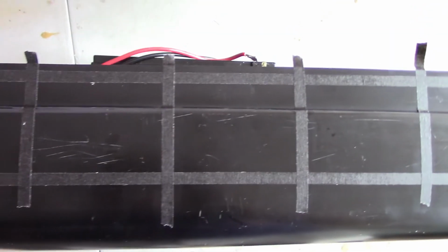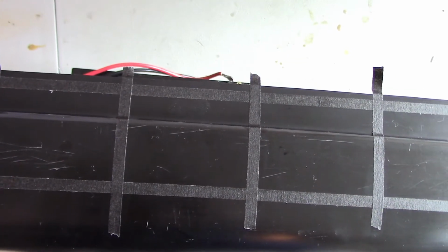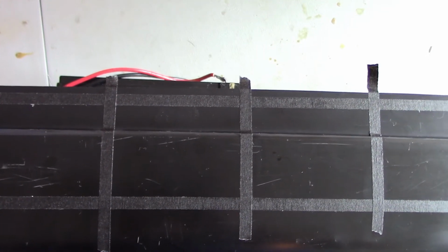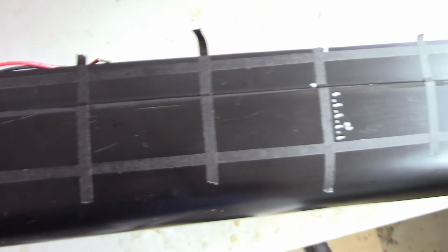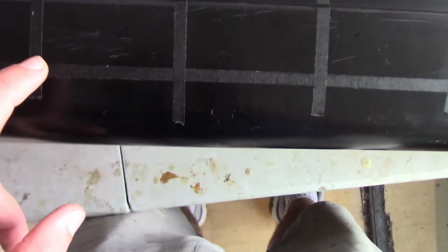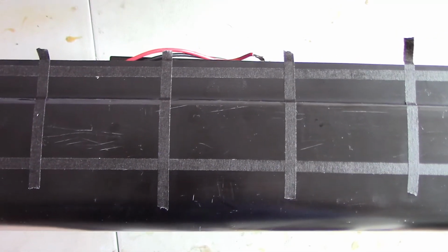The next step is going to be drilling holes in each of the corners of the windows. And that's going to help when cutting with the Dremel. It'll just kind of help break the pieces off easier and have cleaner corners. Because this boat's got a stringer, I'll have to drill holes both above and below the stringer. Typically I use a 1/8 inch drill bit.